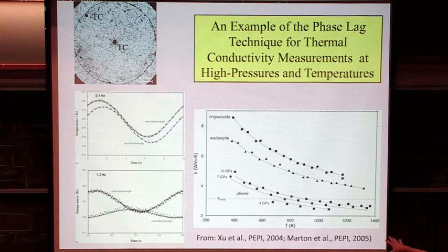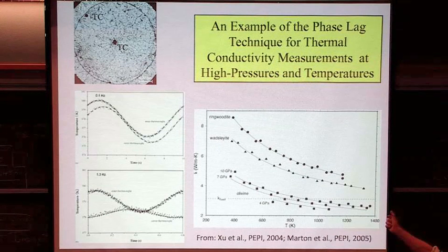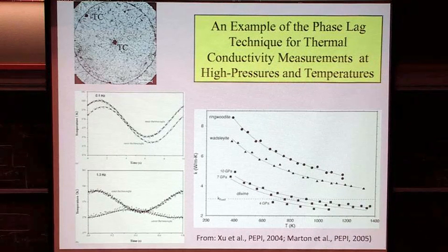But the correction is not that large because we've got basically 400 microns between these, 800 microns, almost a millimeter between these thermocouples. The sample's probably 5 millimeters long. Yeah, there are probably going to be some edge effects, but probably not too invasive. I don't think they negate the measurement, but that's a good point.